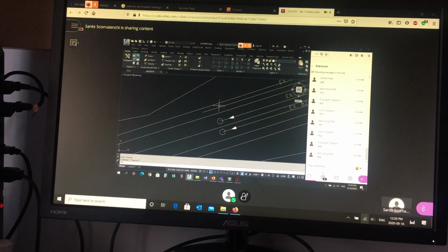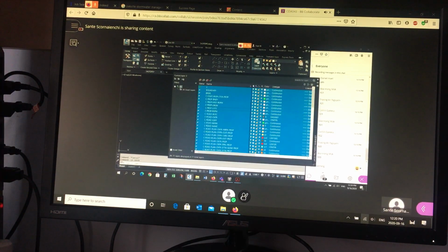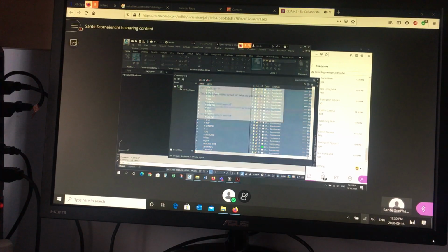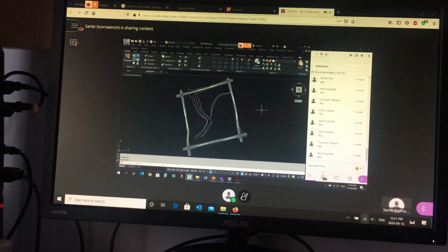is if you go to the layers. So if I go to layer control, turn everything on. So the T-dash water main, now this is where it gets confusing. Anything that's labeled T-dash are actually the lines, believe it or not. So let me select all. T-dash center line. Are actually the layers that have the lines on them. So there's all your lines.